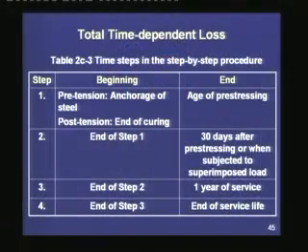The first time step is crucial for the pre-tensioned members, wherein there can be relaxation after the stretching of the tendons, and until the pre-stressing is transferred to the concrete member, there can be a drop in the pre-stress due to relaxation. The first time step may not be crucial for a post-tension member if the age of pre-stressing is right after the end of curing.